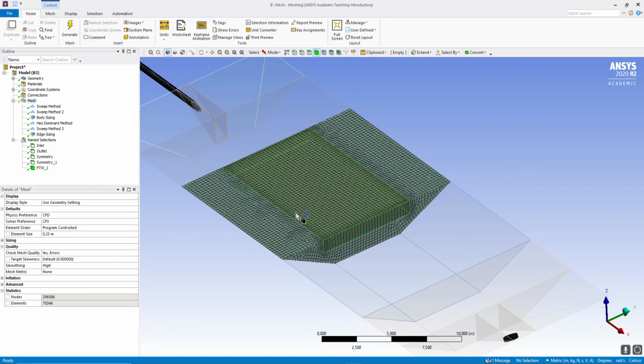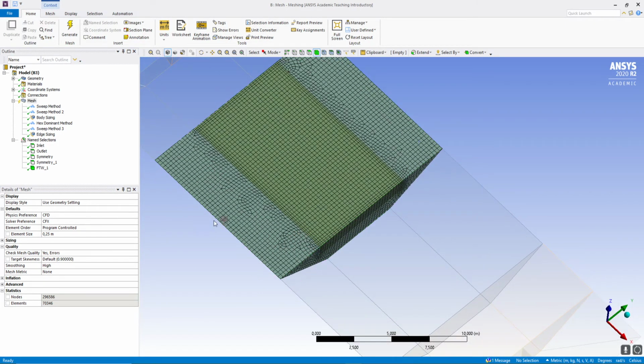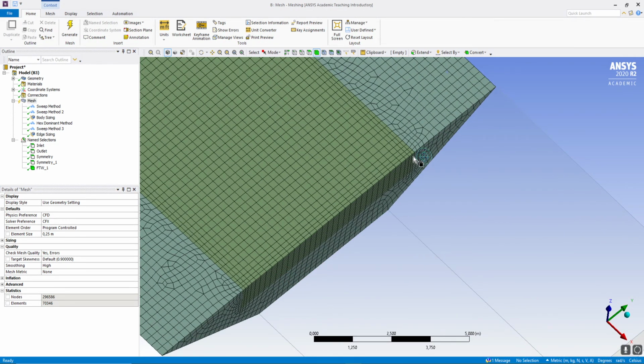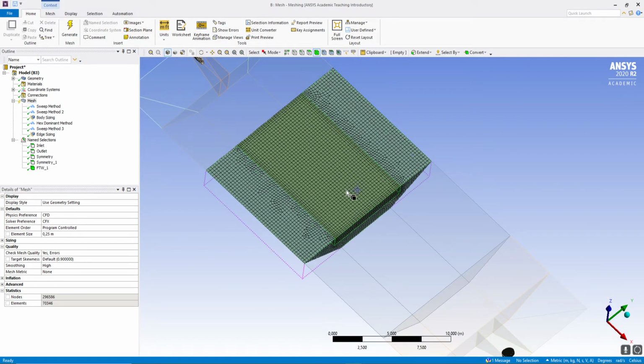We have generated the mesh for this geometry, and you can already see the difference. Remember, the default one had these very large rectangles, very large cubes in this region. Now you can see that it's much closer to the ones that we find here. Okay, and this region is different because it's the contact region, so it's making an effort to fit almost like a puzzle piece in the zone that was generated before.